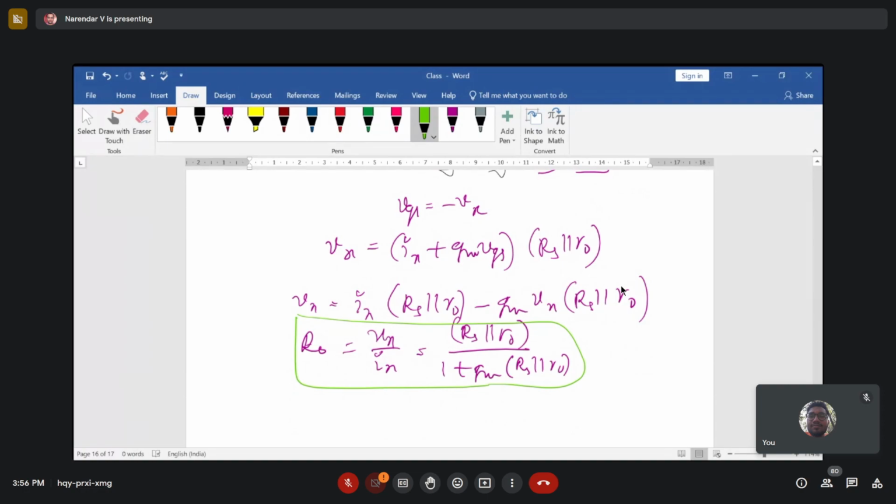So this is the circuitry, and definitely Rin is going to be so high. The input resistance of your circuitry is going to be so high here, the output resistance is going to be pretty small, and the gain of your circuitry is close to 1. So you cannot use this for great amplification of your signal. Okay. So we'll talk about the remaining things related to this common drain amplifier in the next class.